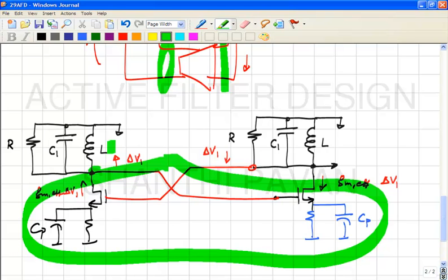Does it make sense? It's a very common thing that you design the transconductor, and think everything is fine, and then you put all of them together and suddenly you find that your whole filter is oscillating. And the reason for that is that common mode oscillations can occur if the common mode feedback loop is not strong enough.